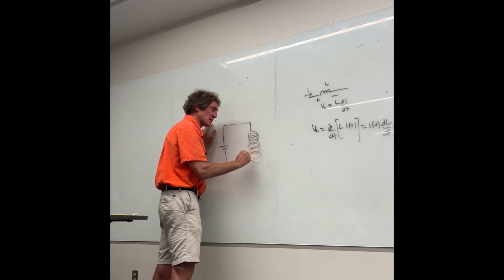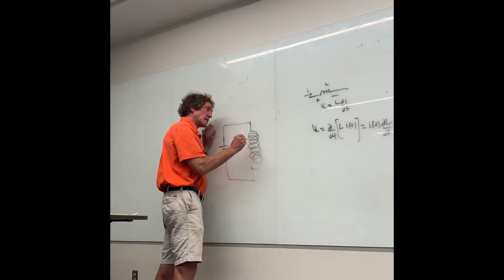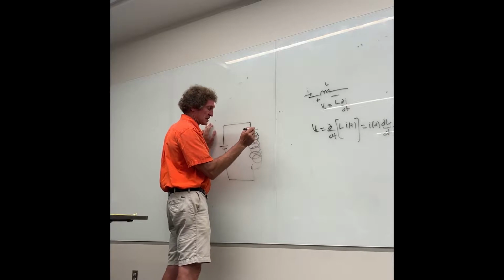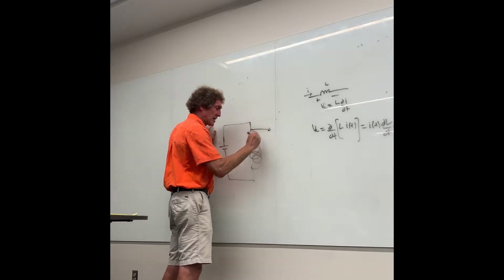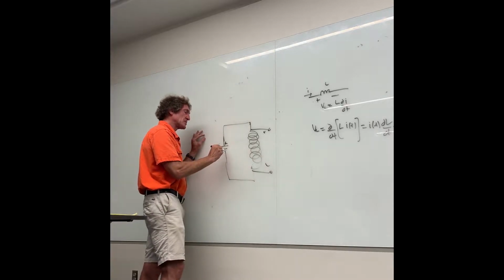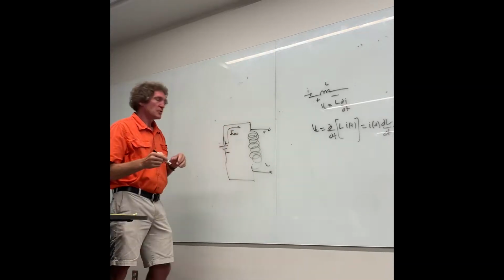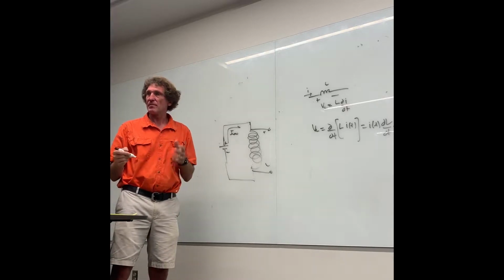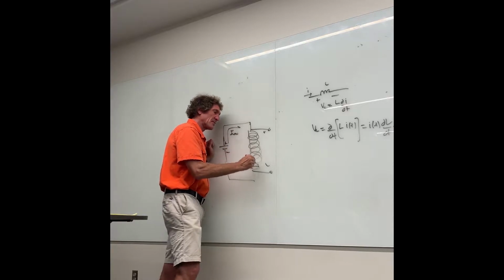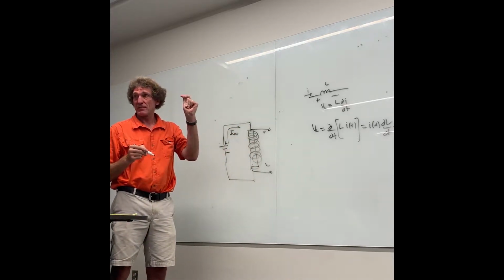through an inductor like so and down. And at the edge right here and here, they'll pull a voltage off of it. Now, they first allow the current to go to I max, and it could be 200 or 300 amps, maybe up to 1,000 amps, all right? And then what they do, they have this thing packed full of a high explosive, and they set it off.